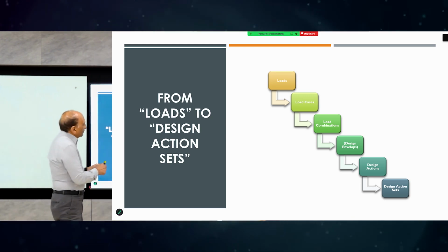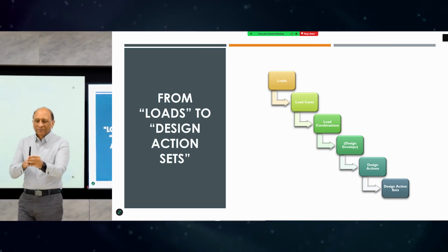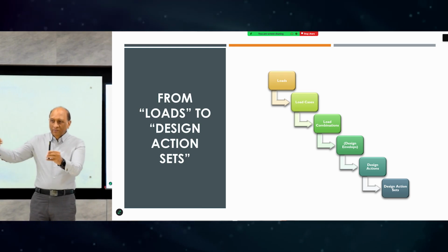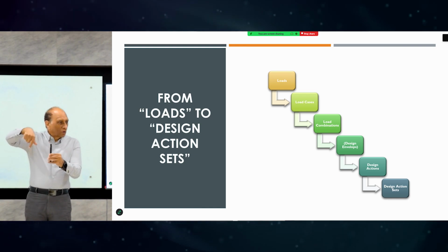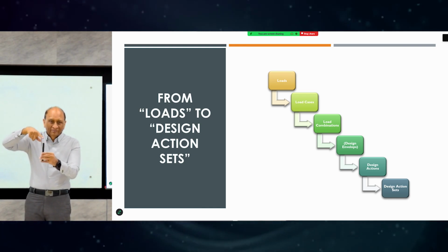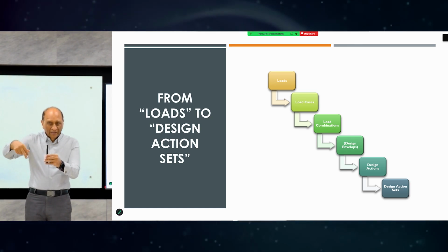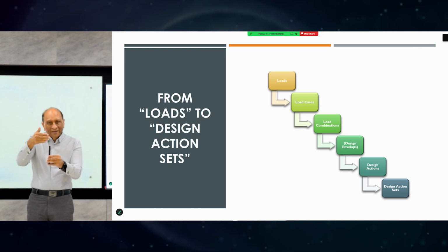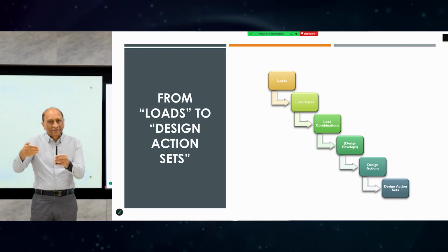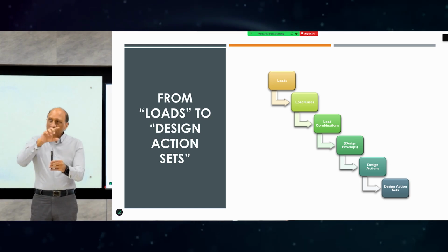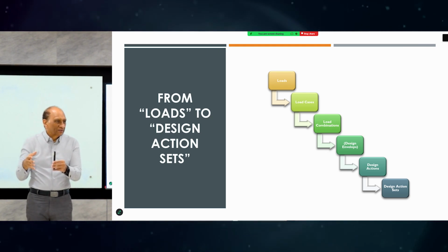So the problem is that from load cases, load combinations are developed. And wind also, wind can be coming from this direction, could be coming from this direction, could be coming from this direction, any direction. So all around wind directions will produce different bending moments in the same column. Earthquake, the same thing. Earthquake can come from any direction. So it could be producing different bending moments depending upon where it is coming from. So direction of earthquake, direction of wind will create those cases from the same load. So the same wind load may have 24 cases of wind directions.